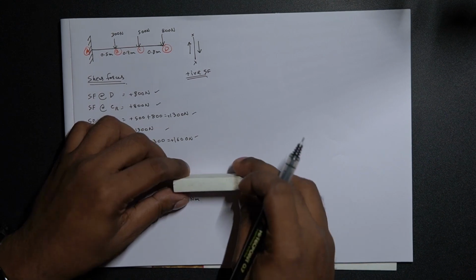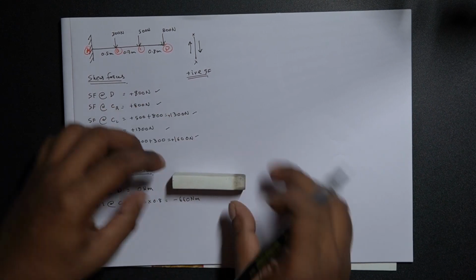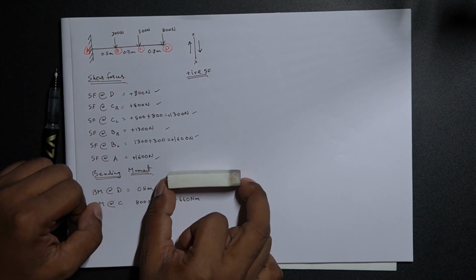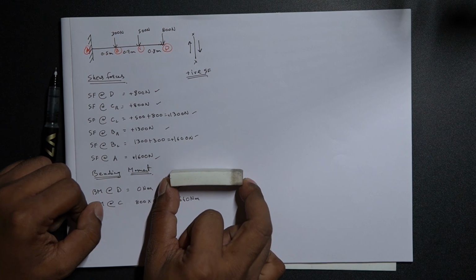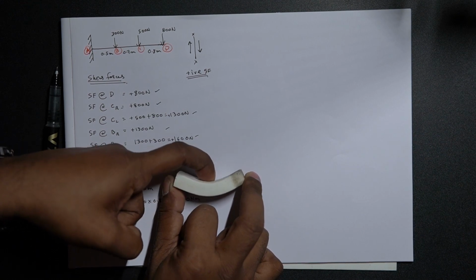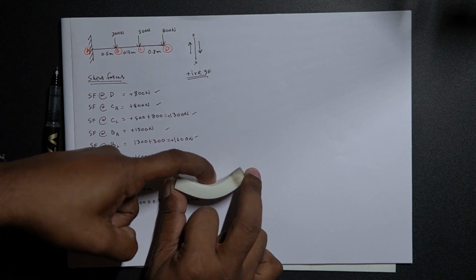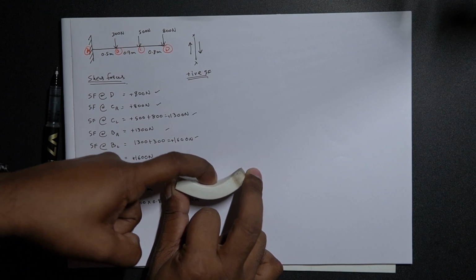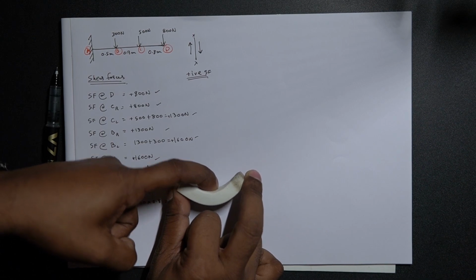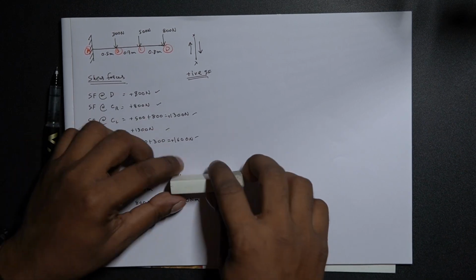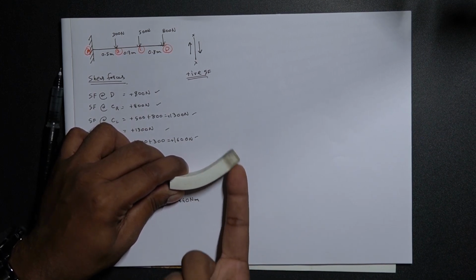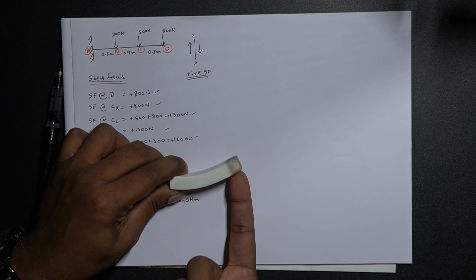For instance, if we consider the same case where this is a simply supported beam, supported with my two fingers, and there is a load applying at the center and the beam is sagging. This curvature which is representing on the top part is creating a sagging moment. So in case of sagging, we consider this as a positive bending moment. Similarly, in a cantilever beam, if the load is acting from the bottom towards the top, it creates a sagging action. So that comes as a positive moment.